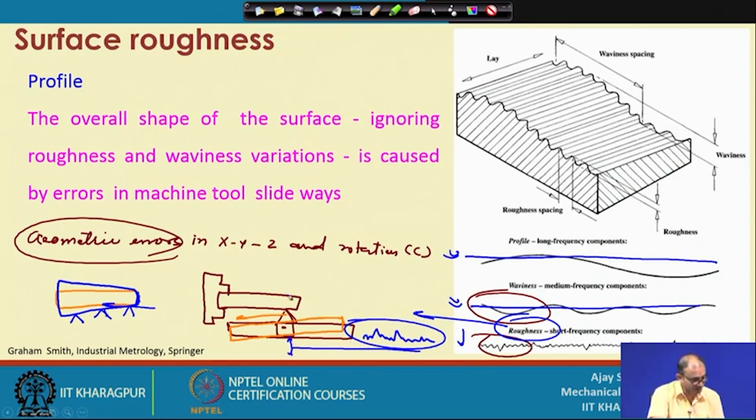because if you see the optical materials, when the light passes through it, if it is a mirror, then it will reflect, and if it is a lens, then it will pass through it. So, if the roughness is as low as possible, then the homogeneity of the light which is passing through or reflected from the surface of the optical material will have the perfectly required dimension, but that will depend on this particular surface roughness. So, smaller the roughness, better is the performance in many cases, but not always. In some cases you always need a surface roughness also.